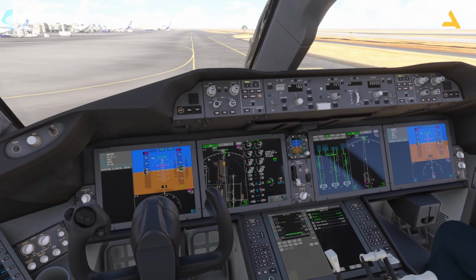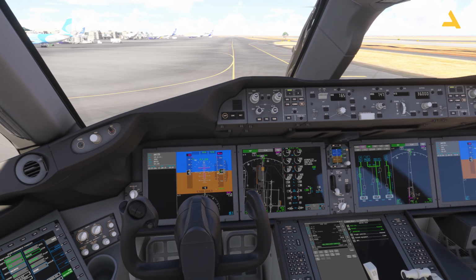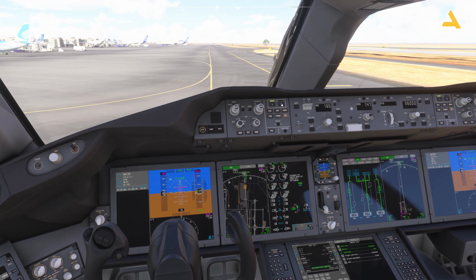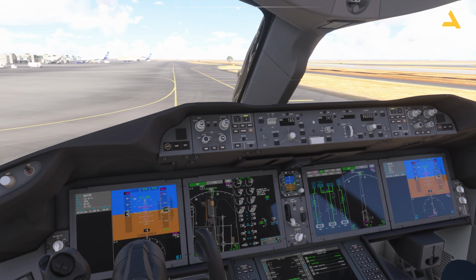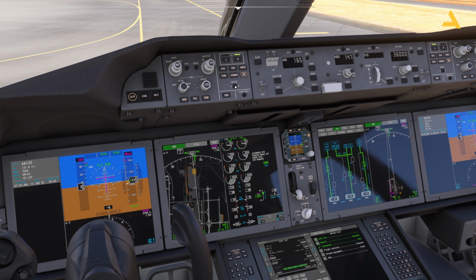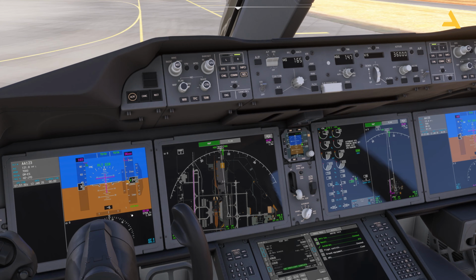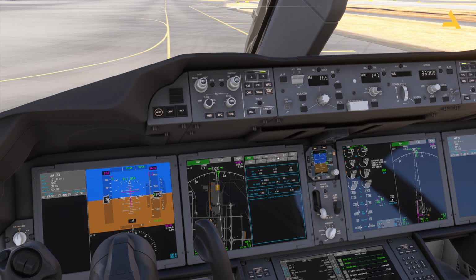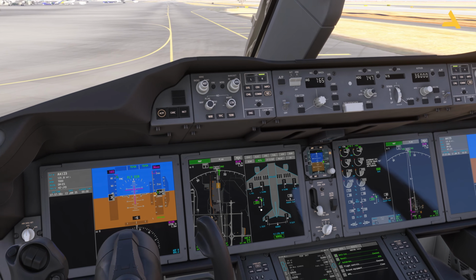And now let's do the flight control test. So just bring up the system. If I press right over here, now I can bring up the system on this screen. Oh, actually the ICAS is here, so I cannot do it over here. I can move it to this screen by pressing this button. Now the ICAS is over here and I have the complete navigation display. Now I can bring up the system, and for the flight control, I can check.